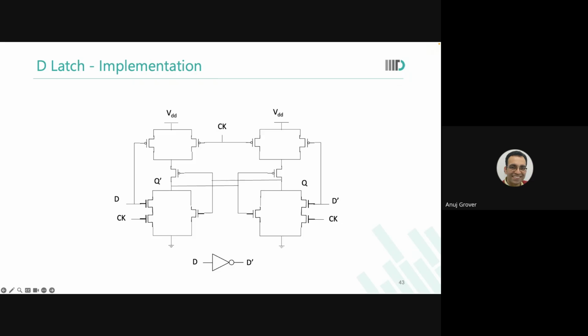But as a designer, you say, I am removing 4 transistors. What it means is I have to take care of sizing. I will take care of it. As a designer, you will take care of sizing. But what you also need to do now is to introduce a figure of merit. You need to check something else. See, until now, what did you only look at? What is the delay? What is the power? Setup time, hold time.